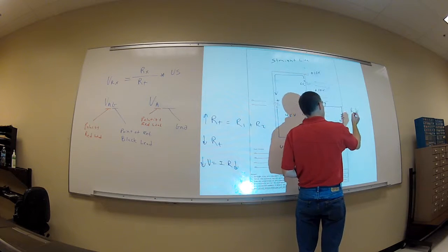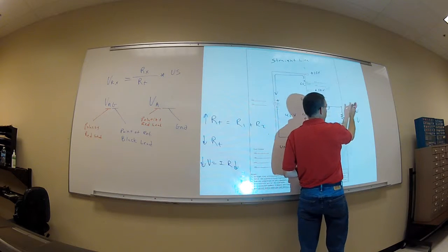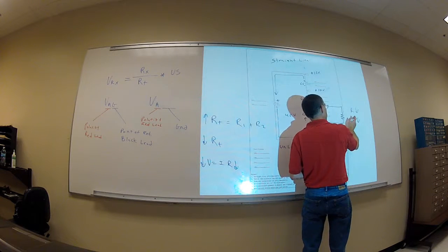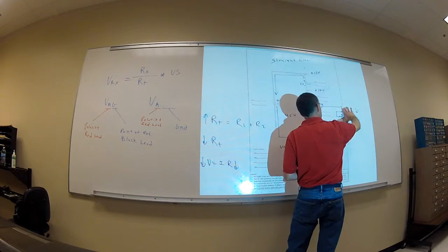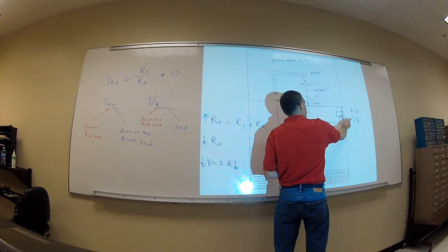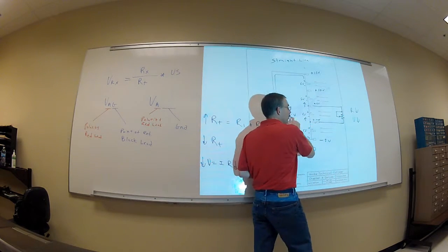some other resistors. Another alternative, and I really want you guys to start getting the hang of doing this, is that instead of plugging in and pulling out different resistors, we can always use our potentiometer as a rheostat. Make it a variable one. So then you can go ahead and put in a variable pot in there, start tweaking it down so you start dropping the resistance of that potentiometer, and watch that voltage until it drops down to that 10% value.